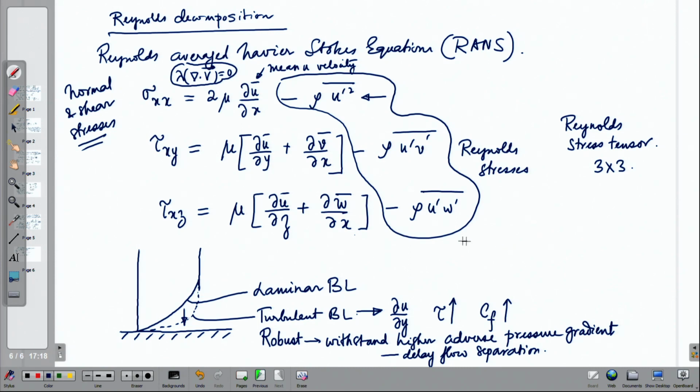So, you may recall that the leeward surface of the airfoil was drawn like this, and we discussed flow separation in that context. The same leeward surface when exposed to a laminar boundary layer may see a flow separation at a point like this, say x laminar, and see a flow separation somewhere here, which is x turbulent.